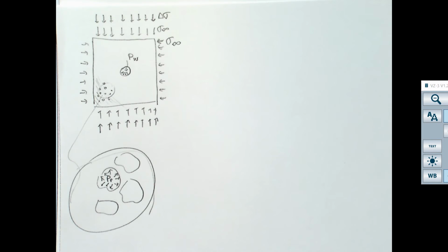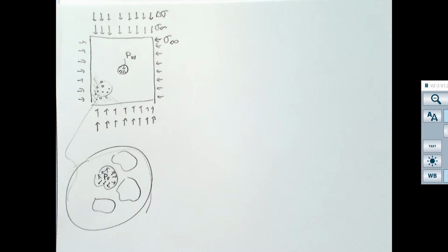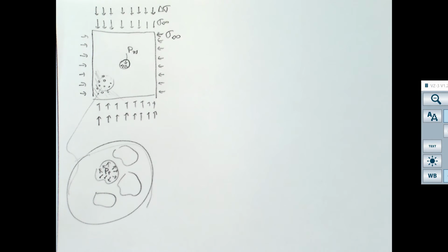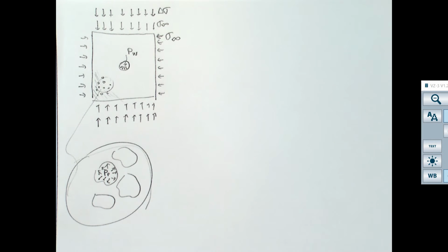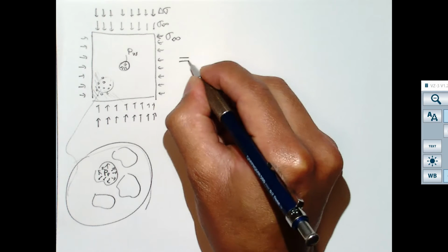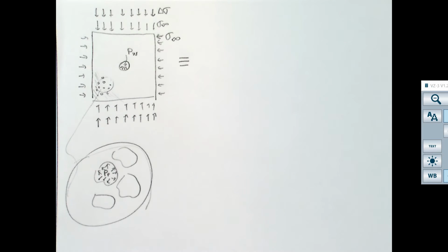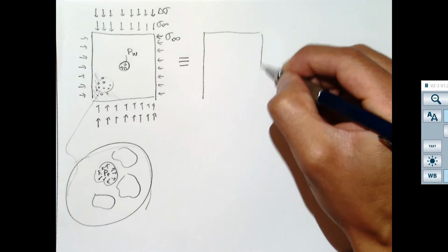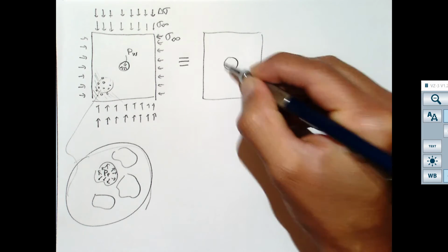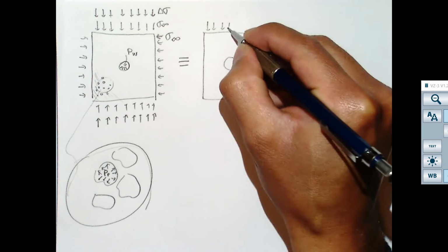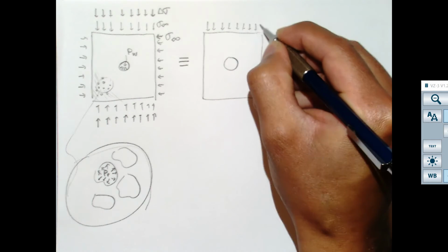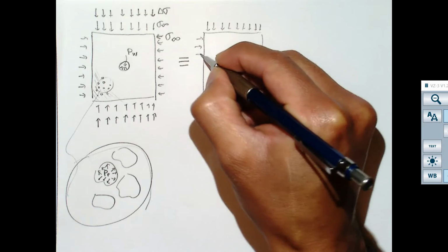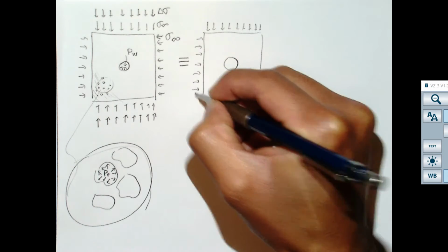The combination of all of those are going to allow us to see and to solve all the stresses in the wellbore. And in order to make it easier, what I'm going to do is to break this apart in all these components. And the first one that we saw, it was what would be the effect of just a far field isotropic stress sigma infinity.